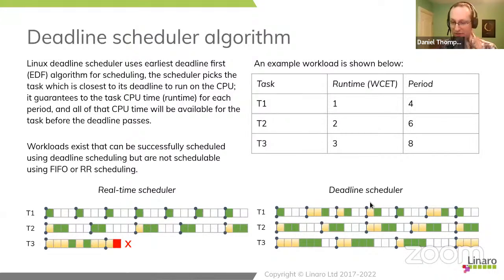You can look at the patterns, you can study them. You're always looking forward to try and figure out what the deadline is, and then you can see which one is the most important in the system at any particular time. So for example, at this time instance here, this task is the lowest priority task in the system because its deadline's a long way ahead, which is why it's deferring to the other tasks.